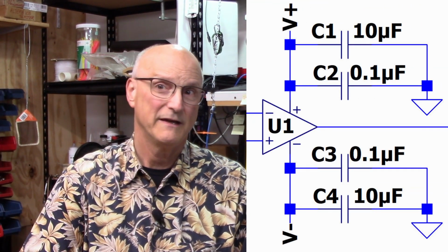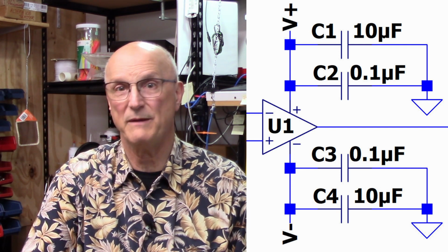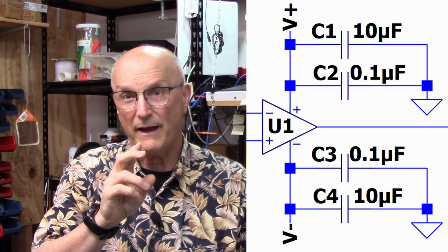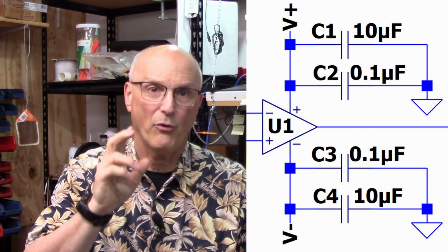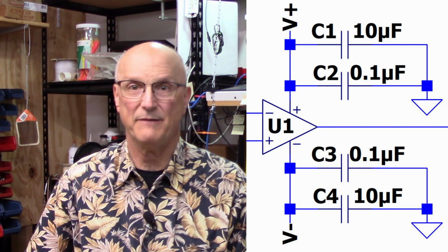And all of this brings up the power supply feed to the op amps and comparators, at least in my mind anyway. Each op amp and comparator chip's power supply pins will be bypassed with both a 10 microfarad capacitor and a 0.1 microfarad capacitor as close to the power supply pins as possible. So, the initial design of the power supply function block is now complete.